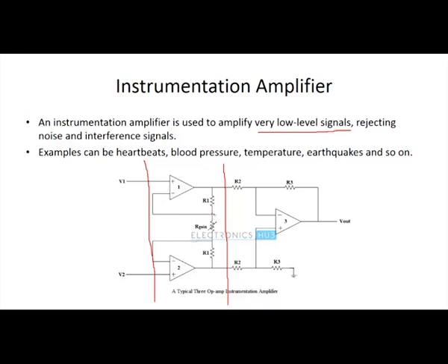So here it is V1 again. By using the superposition theorem, we have to consider only A1. If V1 is given, then what is the output, and if V2 is given, then what is the output. So only for the amplifier A1 you have to calculate two output voltages. Similarly for A2 you have to calculate two output voltages.